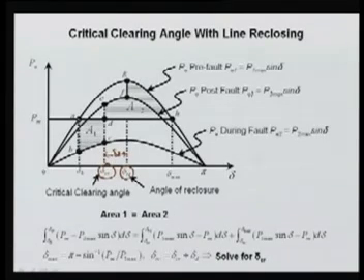So in this case, using the equal area criterion, this area should be equal to your area D, E, F, G, H, D. So this is the complete area we now want to know. So area 1, or you can say A1, should be equal to your area A2. Now this area will be equal to nothing but the integration of PM minus this P2, from here to here.